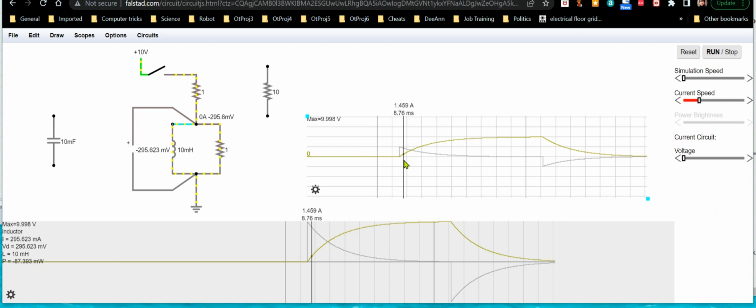And the capacitor, you remember, during the charge cycle, well, the current started out at 100% and the voltage was at 0, so the voltage slowly increased as the current decreased in a capacitor. And when you go into discharge, the voltage is slowly decreasing from a positive level as the current starts decreasing. It starts at 100% and starts decreasing as the voltage also decreases during discharge.